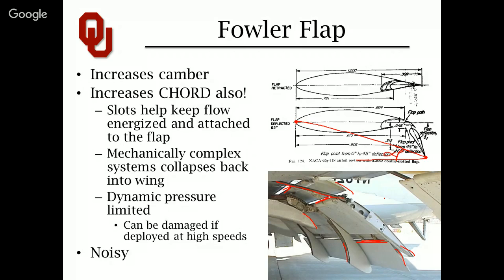So by dropping flaps, you're changing essentially the incidence of the wing, the mounting angle of the wing. You're changing its default orientation on your fuselage so that everything about your airplane stays level, while you get this nice benefit to angle of attack because your trailing edge just dropped down. It's kind of the same effect as just rotating your whole wing around some pivot point as it sticks through the fuselage.